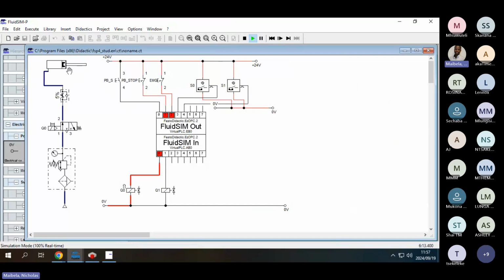This means that your cylinder is constantly going forward. Now, you always want to stop your process. You stop it by using a push button stop or your emergency stop. Say there's another object and you want to also maybe drill it. You're going to want your cylinder to go back so that it can go forward again.